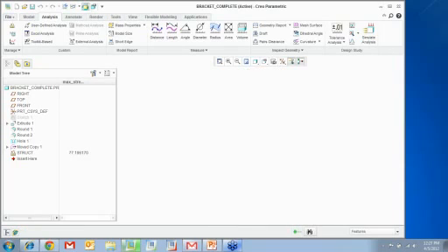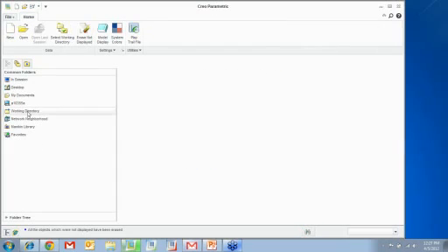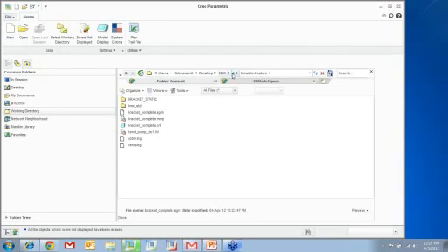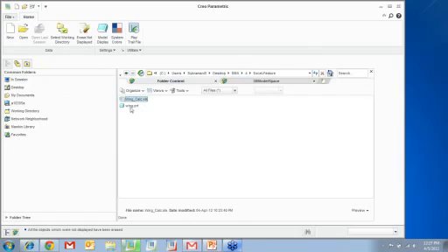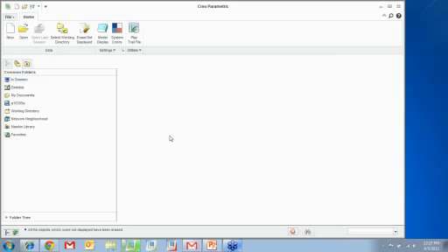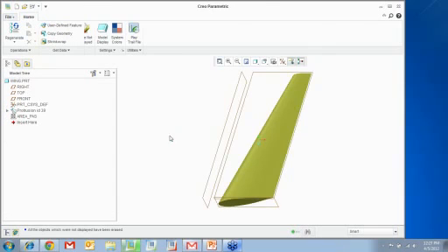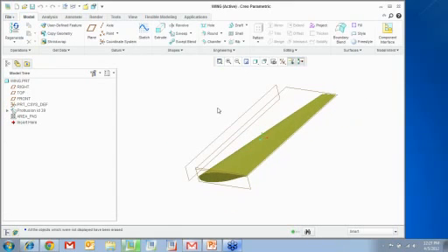All right. So next, after this, what we are going to talk about is something called an Excel analysis. Okay. In an Excel analysis, I'm going to use a wing part. All right. And I'm going to show you, when I change the angle of attack, what is going to be the lift force acting on this. Okay, so I have an Excel calculation, an Excel sheet done, where I'm going to just show you how to use that particular Excel sheet.